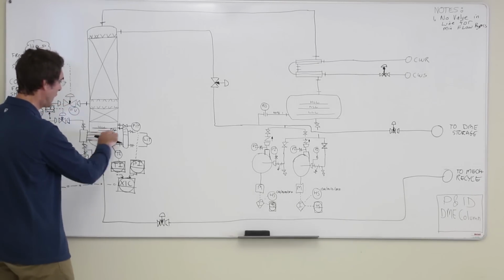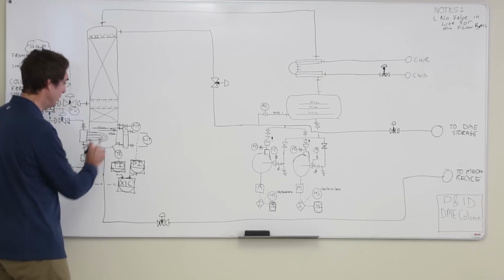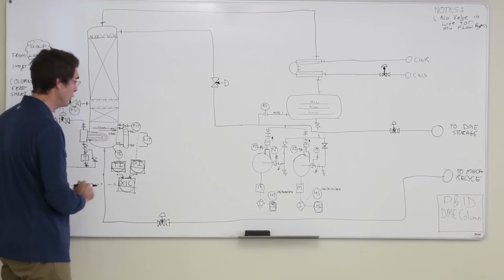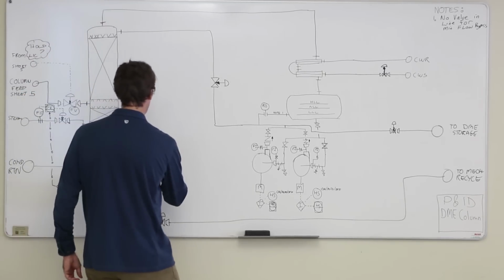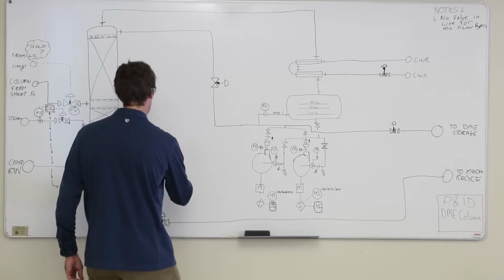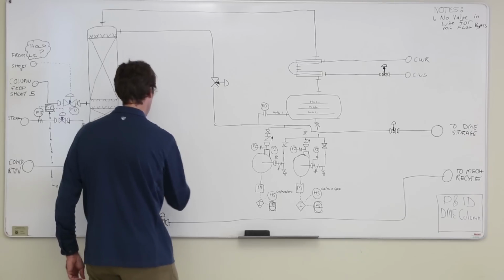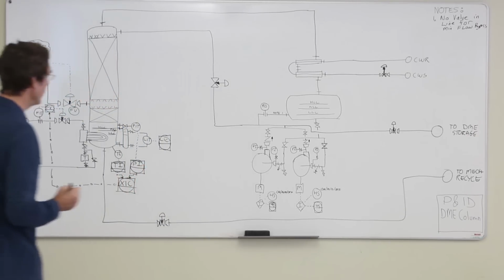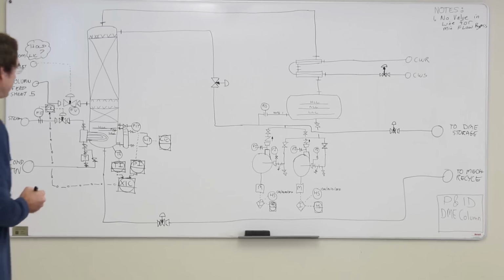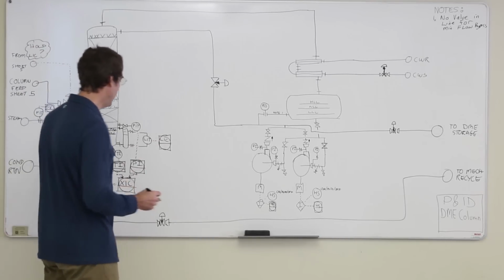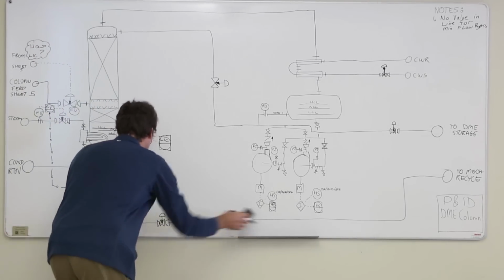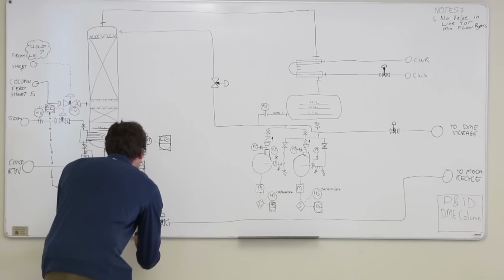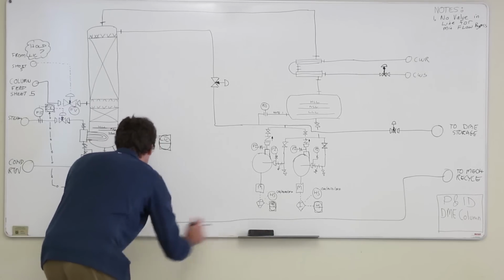I've got the liquid levels above the tubes in the reboiler, so I'm trying to line them up with the tubes in the reboiler. And then we need a level indicating controller, like that. Level is one of those things that we could let float around a little bit. So it'll be a slow variable, and if it is a slow variable, then we need to cascade it into flow again.